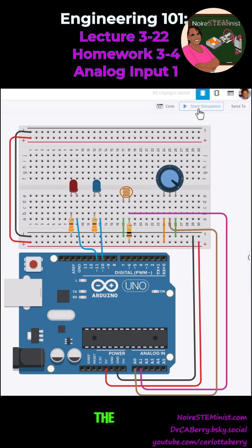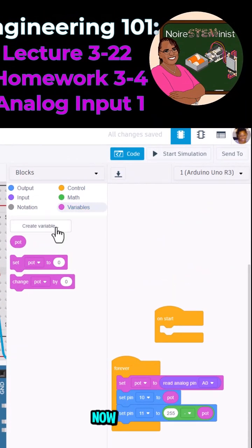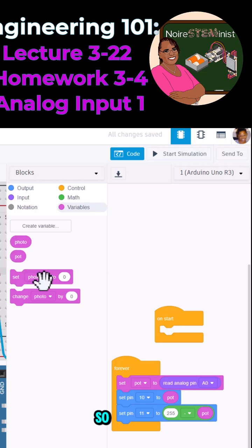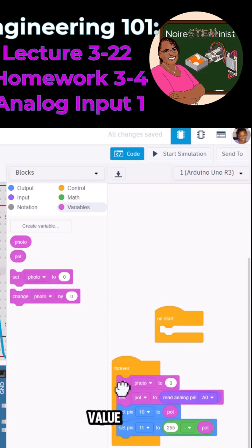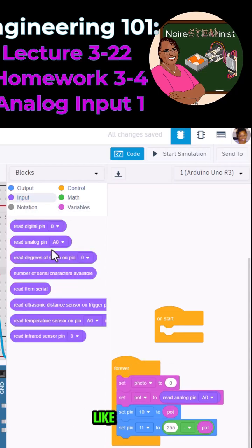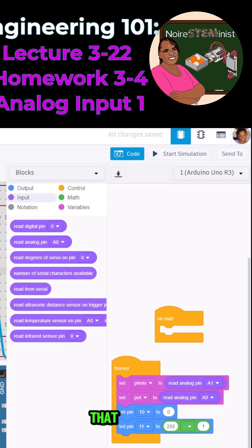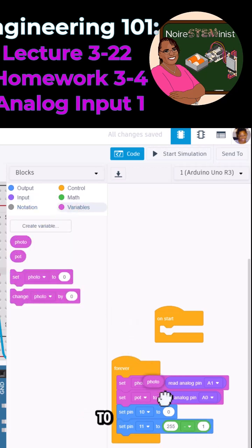And now I will show the same thing, except now I will write the values to the photoresistor. So the brightness will be dictated by the value of my photoresistor. So this would be like a light dimmer or a night light as well. And I am going to use the brightness in order to control that value. And now it's going to be on A1 instead of A0.